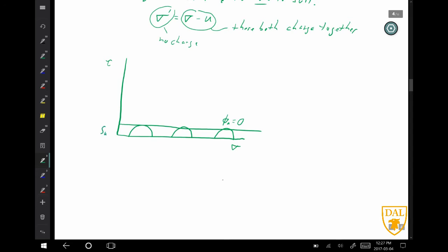And the undrained shear strength is sort of the intercept of this line with the tau axis, or kind of similar to cohesion. But it's not the same as drained cohesion. That's an important point. It is its own parameter, SU. And it accounts for all the behavior in the sample, including the behavior of the pore pressure, all accounted for by this one parameter, SU.